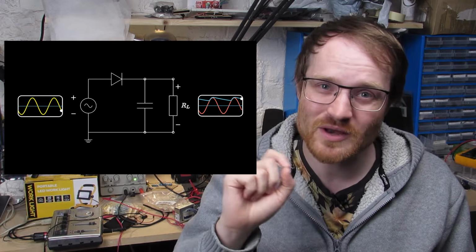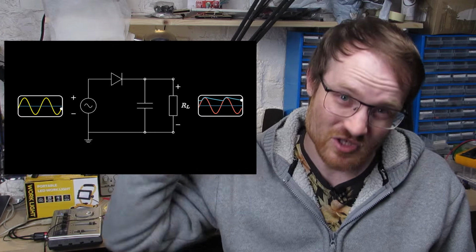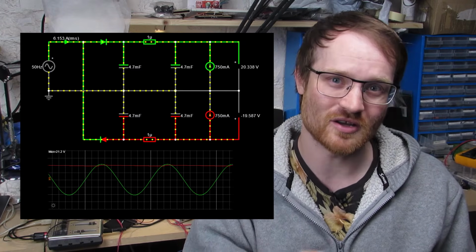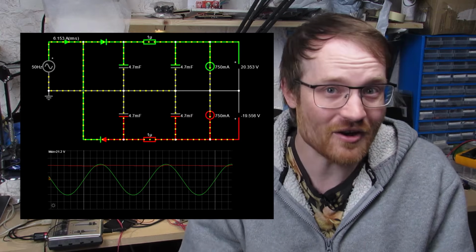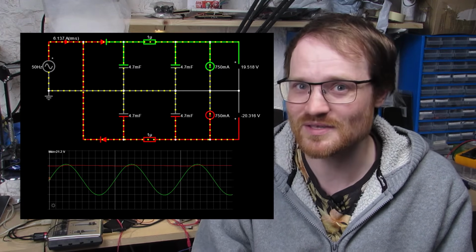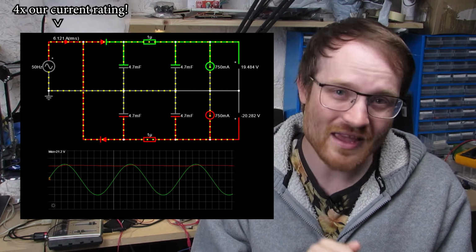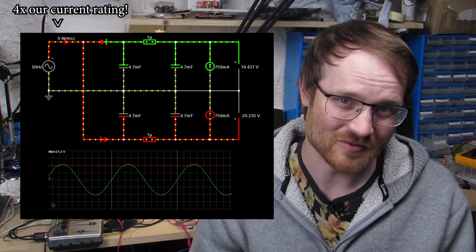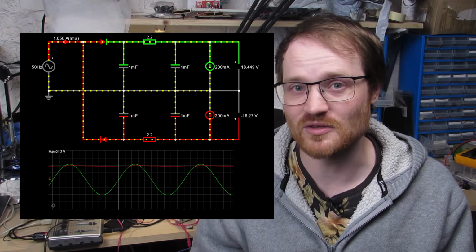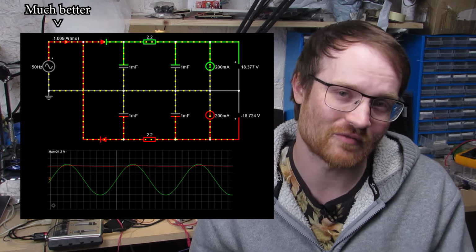So there's this tiny window, only a fraction of the cycle of the sine wave, where we have to shove all of that charge onto the capacitor, and the rate of flow of charge is current. Essentially we get these big spikes of current that are way above our 1.5 amp threshold if we're not careful.